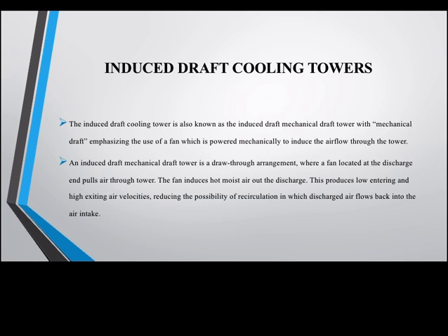An induced draft mechanical draft tower is a draw-through arrangement where a fan located at the discharge end pulls air through the tower. Like I said, the fans at the top of these towers are the ones pulling the air through the tower, to the discharge end, which is the top.